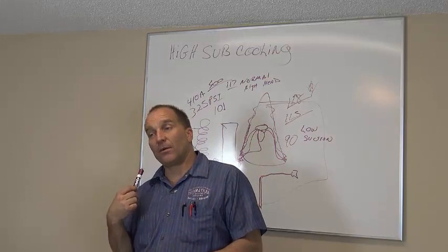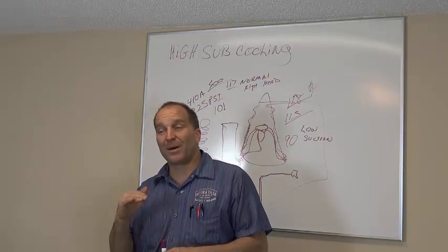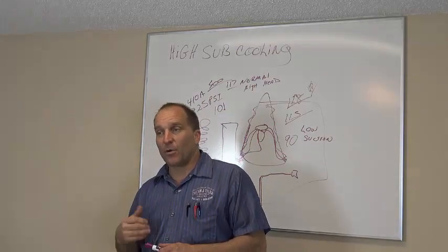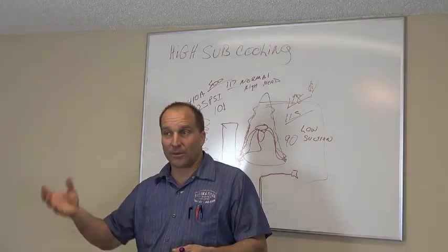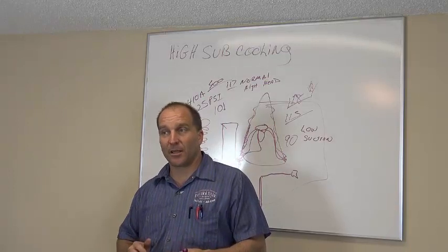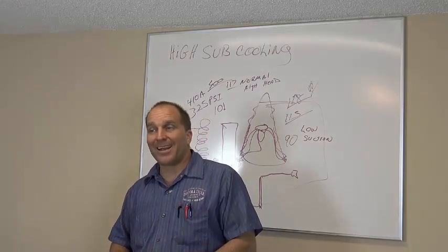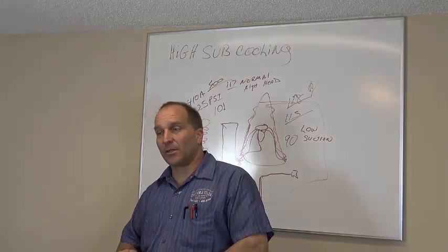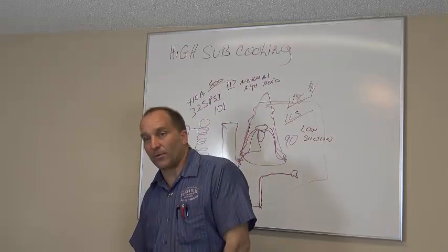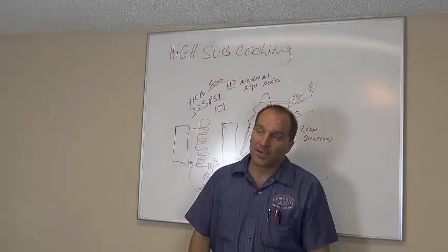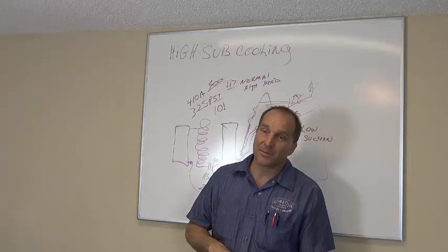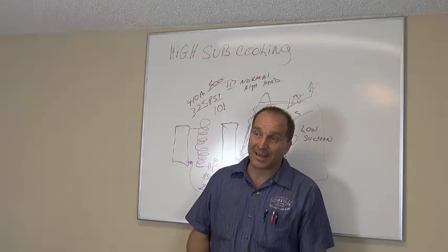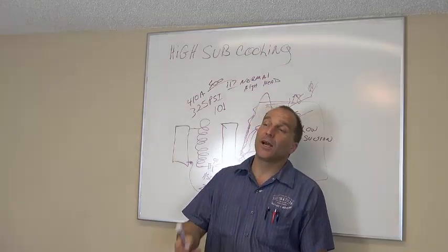Because if you have a 410A system, you might want to do it about 8 degrees first. If you have a 410A system, you're letting liquid in, right? Because your tank is upside down and you're sucking in liquid. Now you bring it up to about 8 degrees, then shut that system off and let it run for about 10 minutes. Why? Because the liquid that you just put inside that system has now got to evaporate into a gas. So now you just jacked your head pressure up.